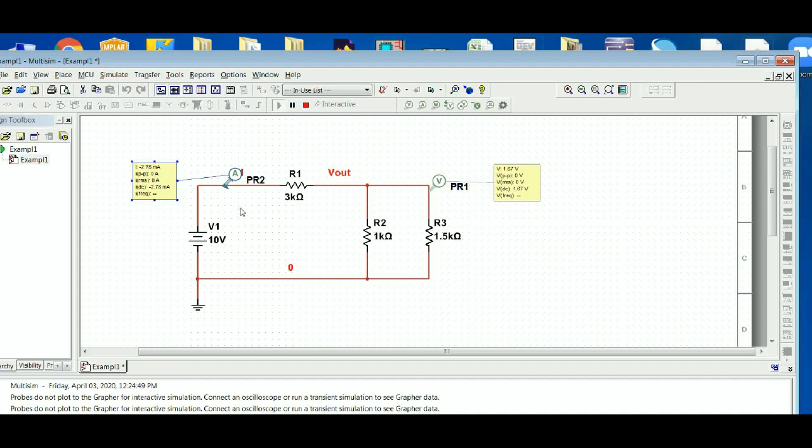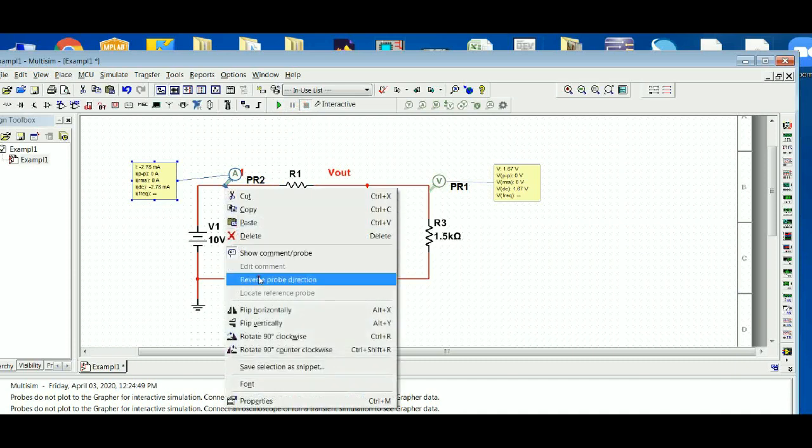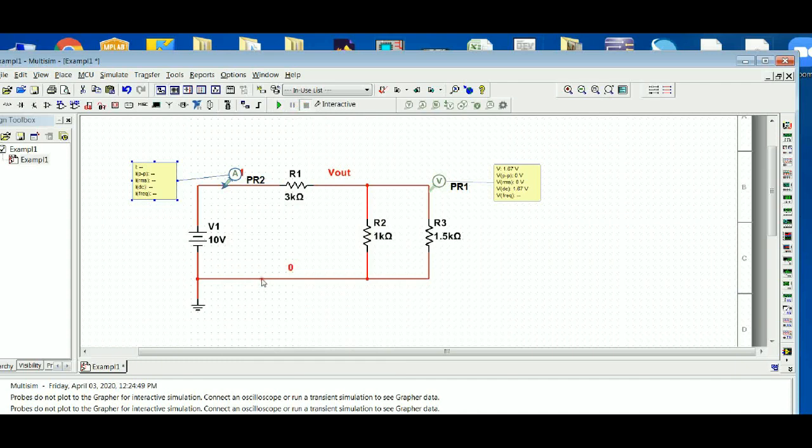The reason it's negative is because the conventional current in the circuit is flowing this way, and we've got the current probe in it saying that we're expecting a conventional current to flow in the other direction. So that's easy enough to fix, and you just have to be aware of that and know what the negative means if you pull one up.